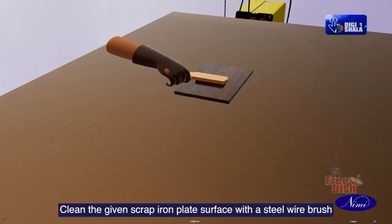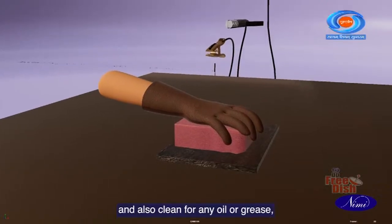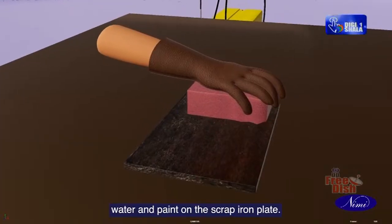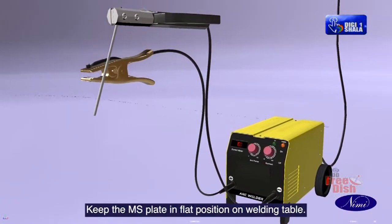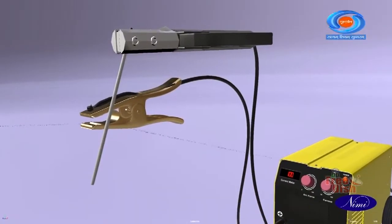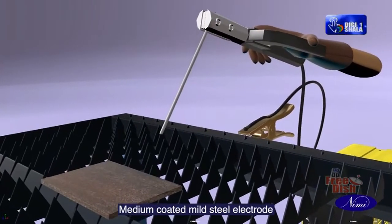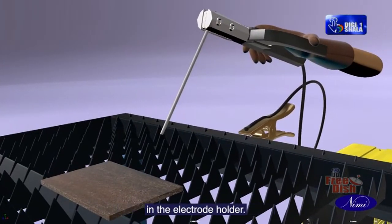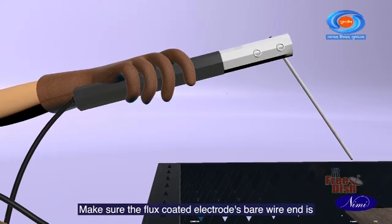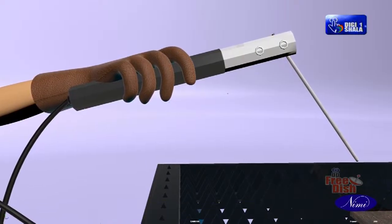Clean the given scrap iron plate surface with a steel wire brush. And also clean for any oil or grease, water and paint on the scrap iron plate. Keep the MS plate in flat position on welding table. Fix a 3.15 mm dia, medium coated mild steel electrode in the electrode holder. Make sure the flux coated electrode's bare wire end is firmly seated in the electrode holder's slot or groove.